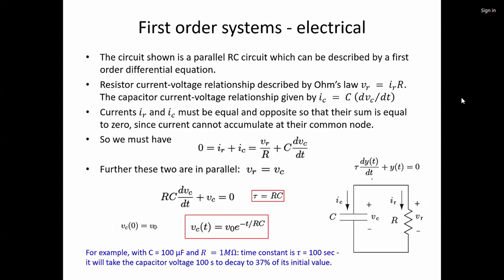Professor, I have a doubt. I'm sorry to interrupt you. Suppose, sir, we are measuring the temperature of a surface, okay? And you told that before you record the temperature, you should wait for one time constant so that it will settle to a steady state, and then it will give the exact value. Now, for example, suppose I have a system in which I can vary temperature instantly.